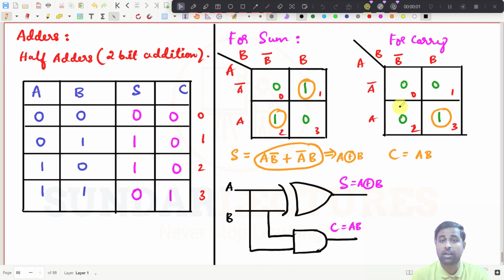I don't need to draw this K map, try to understand. See this equation now, it is 0, 1, 1, 0. Inverted inputs getting output as 1. What is this? This is an XOR gate. So you can straight away put A XOR of B. And you see this one now, 0, 0, 0, 1. What is this output?